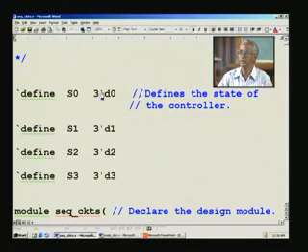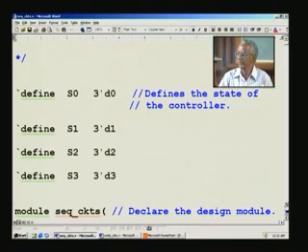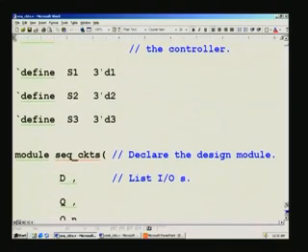And once again 3-bit binary, because the maximum we can have is 7, right. So I just put this, and probably you can correct it to 2, because if it is going to be 3, 2, right. I will check it up later on, but you can straight away correct it, because right now I have listed only this, in which case you might have to use a default. If you use this, ultimately a case statement you will be using for the state machine, and therein you have to take care of using a default.